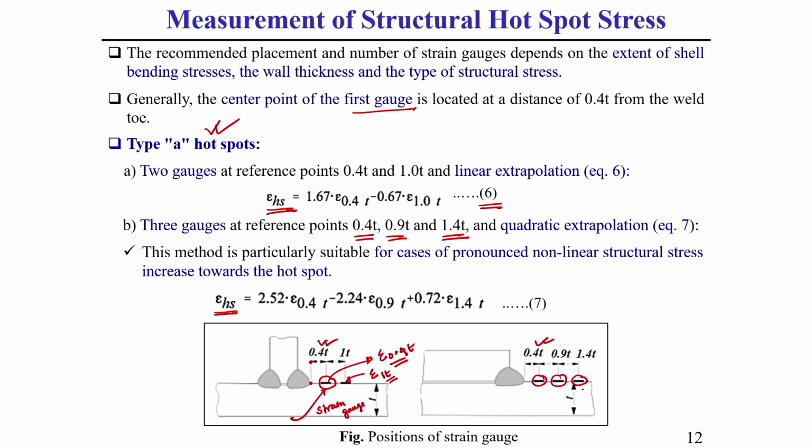Now, once this strain gauge is subjected to some loading, it will either expand or contract. If it is a tensile type of load, it will expand. Due to this expansion of the strain gauge, we can find out the strain value at that location. You know how a strain gauge looks, it is an electronic device, it looks just like this. After polishing that location, we need to insert the strain gauge at that particular location.